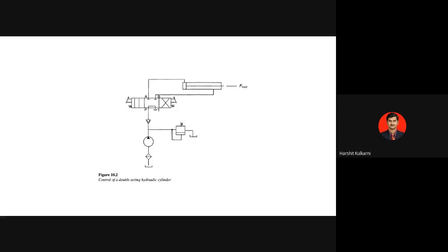So presently you are in center position. That's why I told you that word, spring centered. Normally it will be in the central position and it will be hydraulically locked. This entire system is hydraulically locked. Means there is no flow inside this blank end, there is no flow outside this rod end, nor is there a reverse flow. Nothing. It's just in off position. Off means the actuator is off. But still the pump may be pumping the fluid. But in that case, what will happen? It will directly go to the tank at this present position. Now, did you understand how to name the DCV?